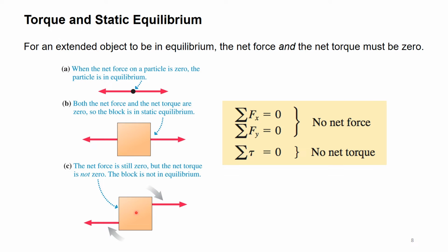So think about this. You choose a pivot for this box. Suppose you choose it right in the middle where the cursor is. Imagine you fix a pole through this middle, and then you pull the box along the arrows. So you pull on both sides along the direction shown by the arrows. The box doesn't stay at rest, the box rotates in a clockwise direction. That's because the two forces generate clockwise torques and they don't cancel each other out. They would have canceled each other out if it were like the second picture, if they lay along the same straight line.